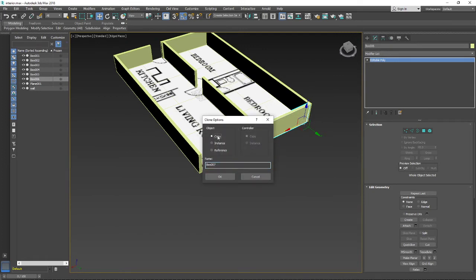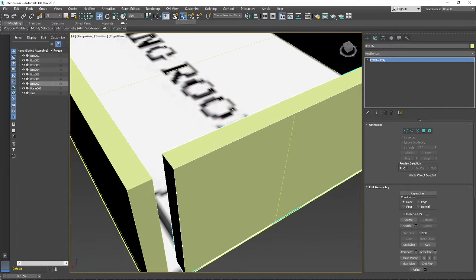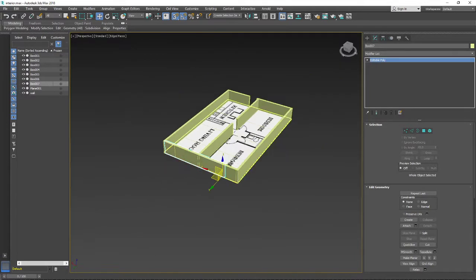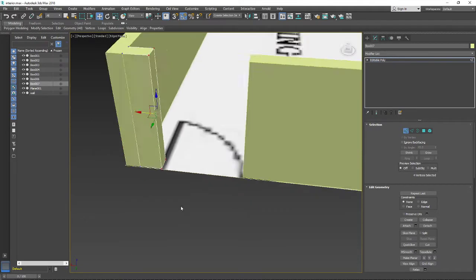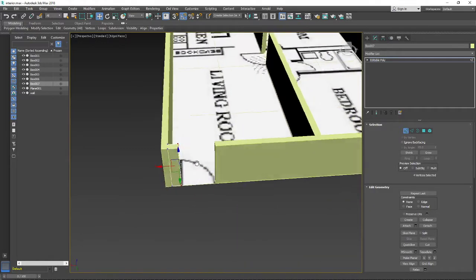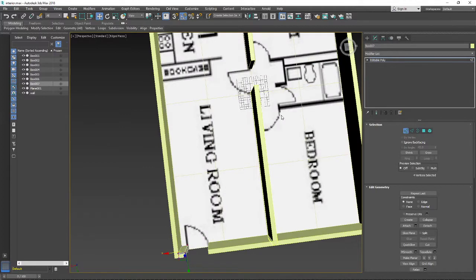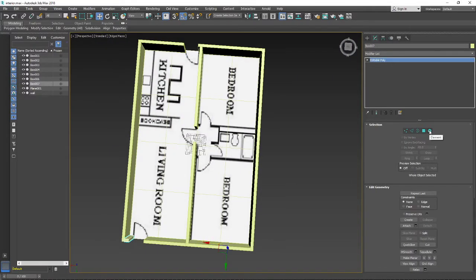Now you can just choose the copy here, and by pressing that snapping toggle you can just snap it to the angle. That means that in each angle we have verticals. So yeah, basically like that. This is overall all the walls. Not all the walls. Let's continue with those small walls over here.